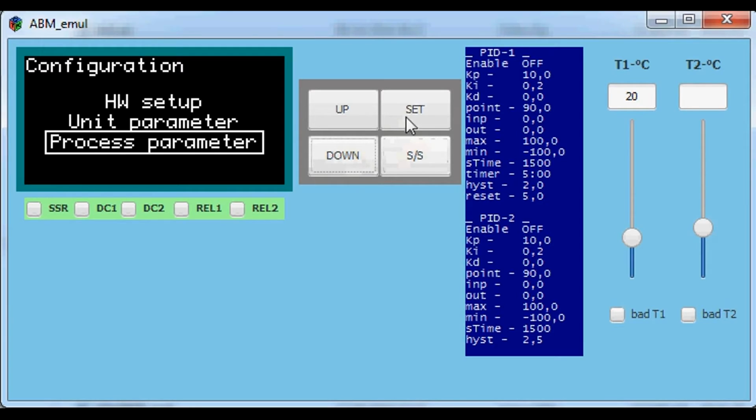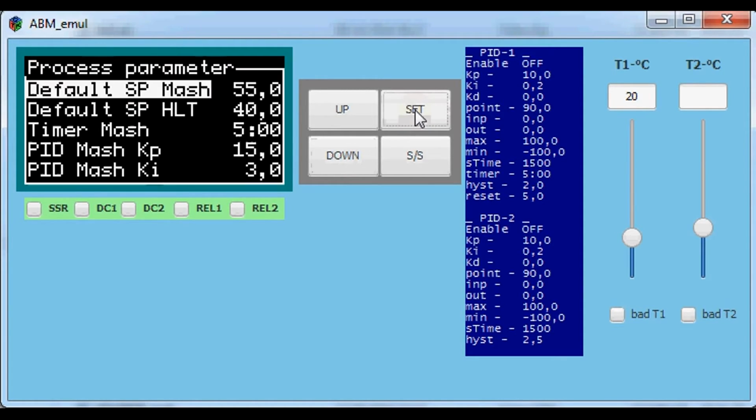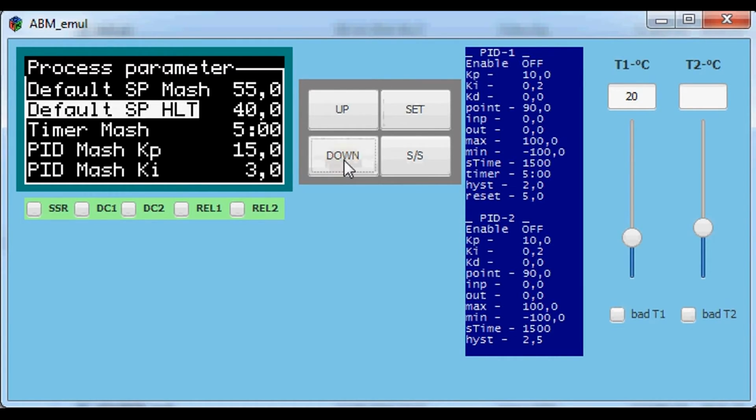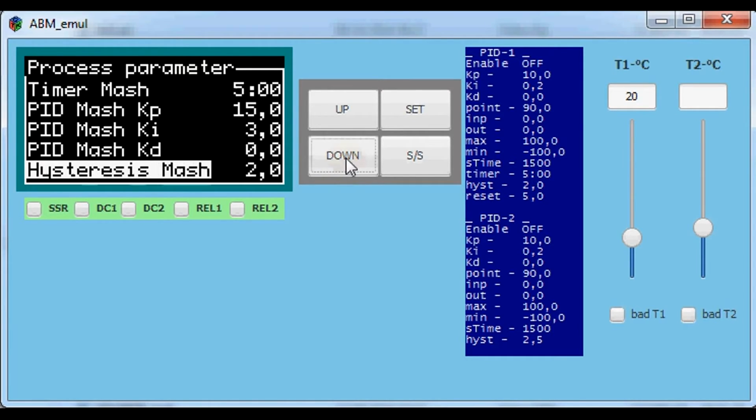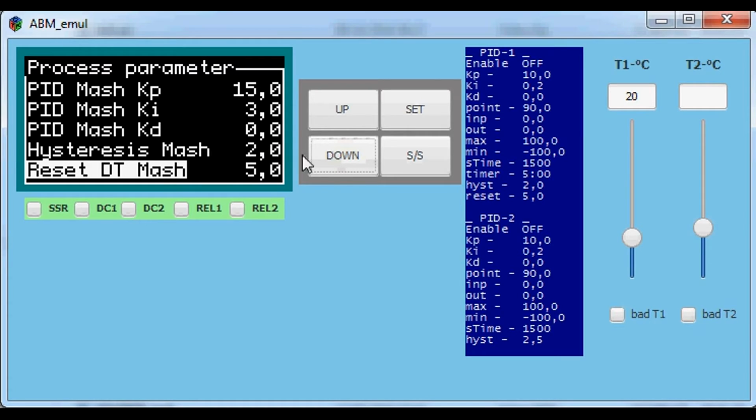That's all. Now the process parameters, which are quite specific for this type of process. The first set of parameters is typically used in manual mode, so you can skip them. These are default temperature, time, etc. Then you have all the classical constants for the PID algorithm, or the hysteresis in seconds for the on-off algorithm.